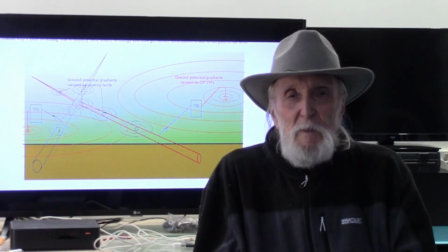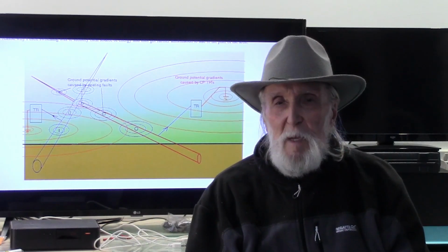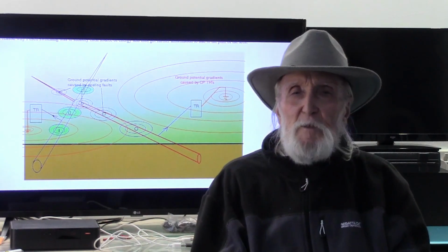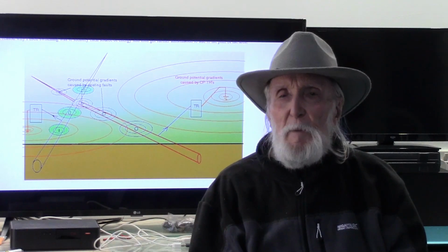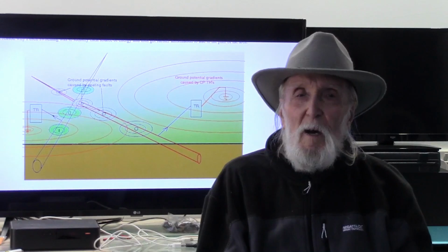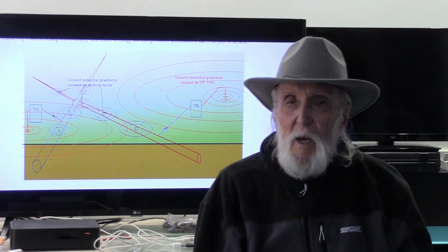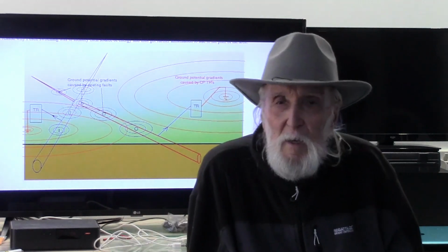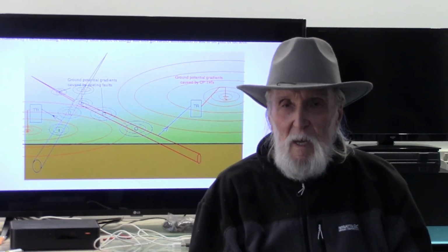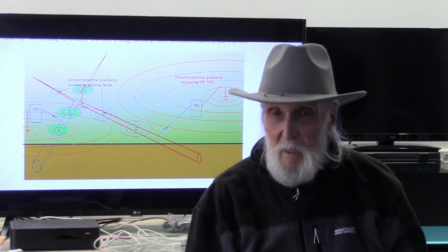Proximity to foreign structures. Foreign structures include pipelines and anything that could cause a disturbance to the natural electrical equilibrium of the ground itself. The two half-cell surveys and DCVG compare the potentials on the surface of the ground and are included in the following link, and you will see a link button.